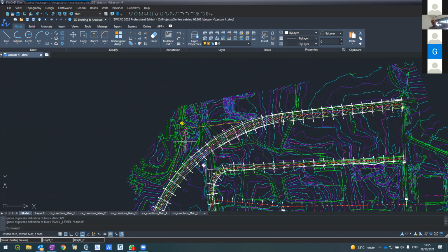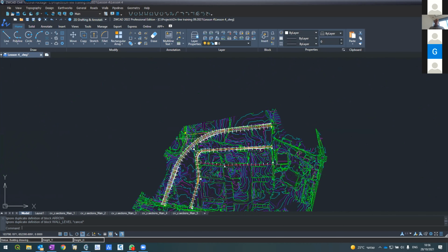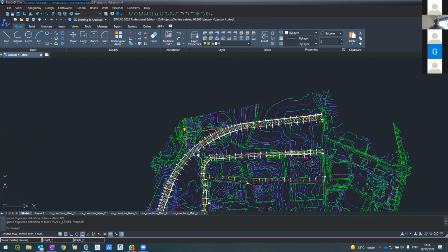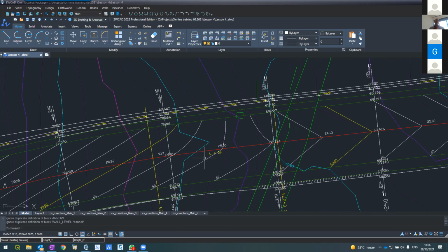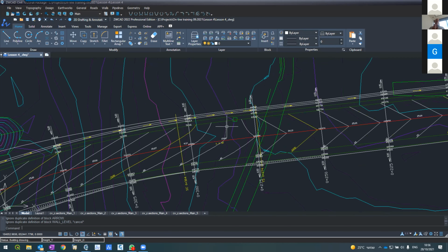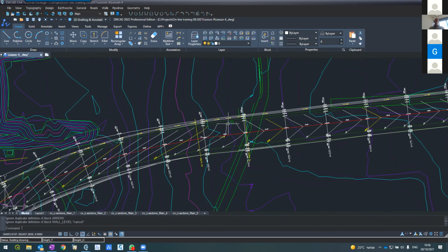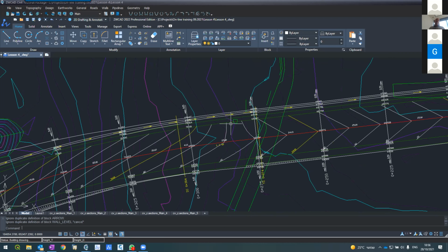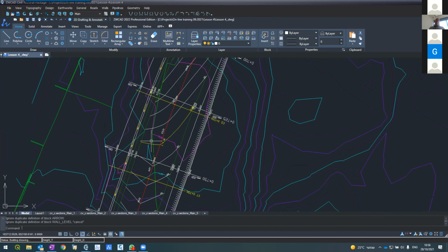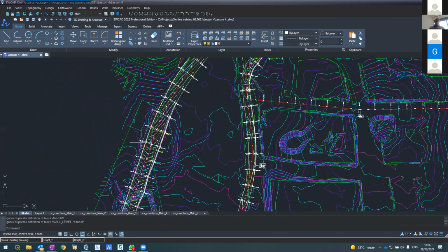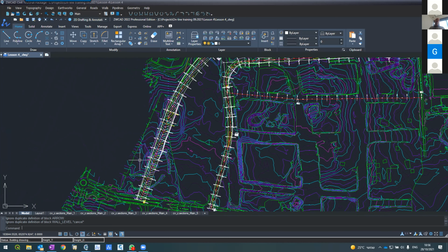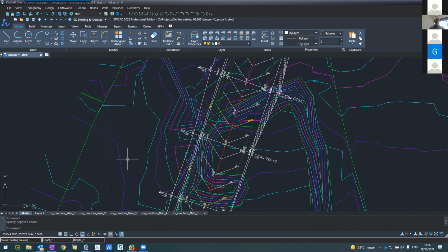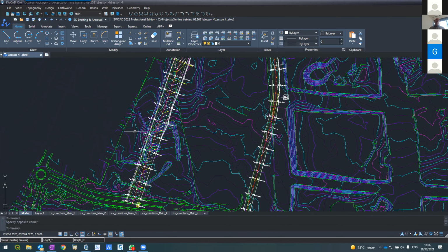There was a question raised by Rose from RCC, how to add an IP. So I'll do two things here. First of all, I will increase the length of the transition from 30 to 40 meters, because you remember I had the error alert from the system. I'll do the same here, 40 and 40. And I would also add a new IP here. I would break the road going into here, this point, and from here go straight. So I'll change the alignment completely.